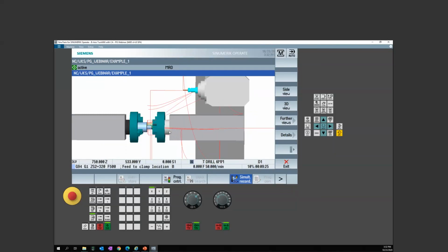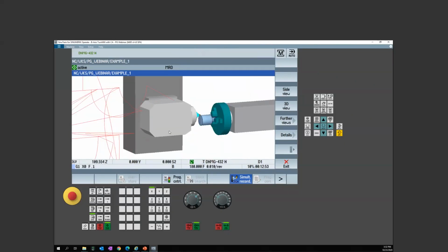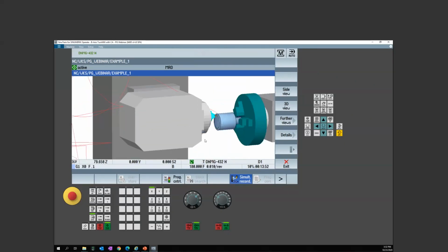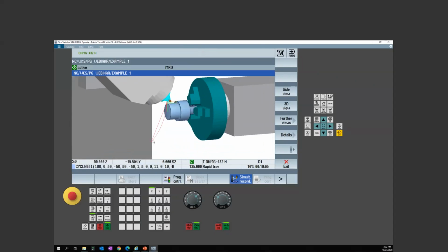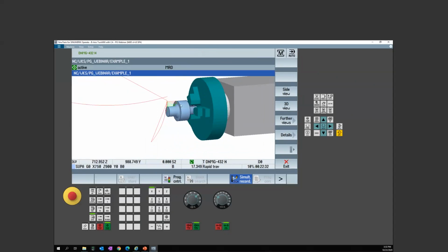Now you'll notice right here, when it gets done with the transfer, it's going to change my display. That was that display command I showed you. So now we're at our B0. We're using head number 2 for our tool carrier. I flip it. Now this is a case where maybe implementing a retract in the cycle would keep me clear. That was real close. I could have clipped that. That is what we call pucker factor right there.